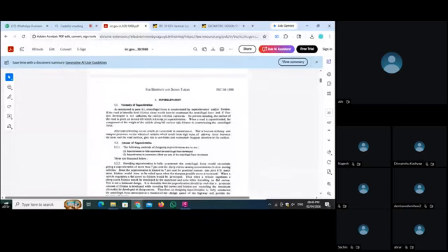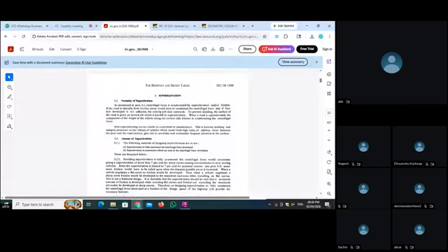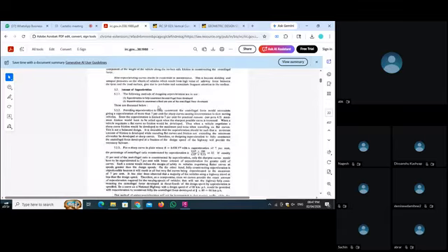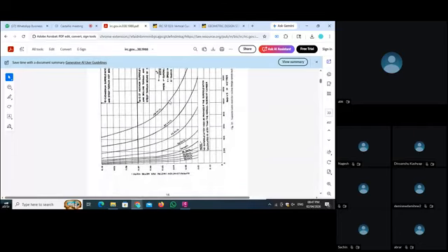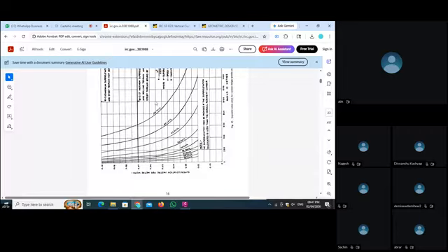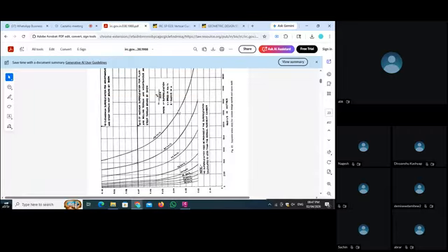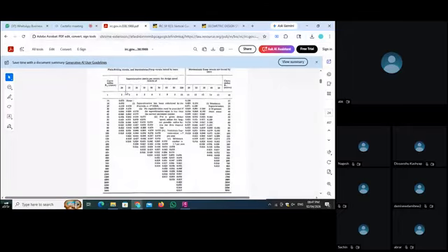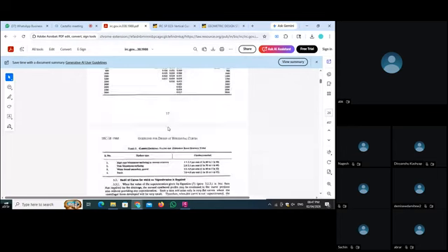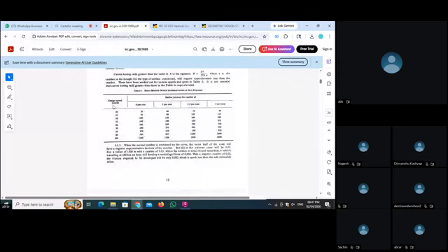The purpose of showing you this code is how to read a code whenever you see one. In super elevation, you can check all the theory. What is the super elevation? How do they calculate the super elevation? The variation of the curve is provided, with all the details as per the speeds and as per the radius. So they provide all the things here. For the design speed, if the radius increases for 4%, 3%, 2.5%, what is the difference in the super elevation values?